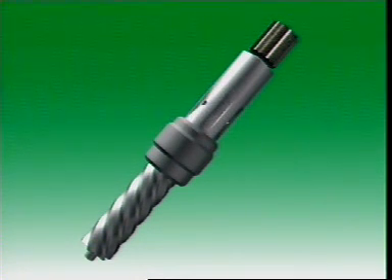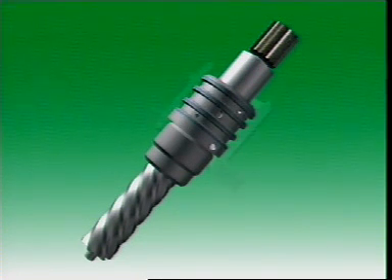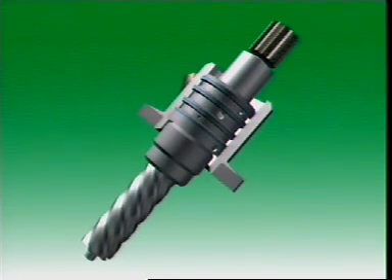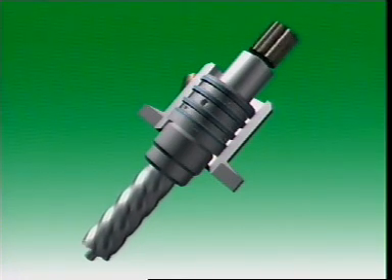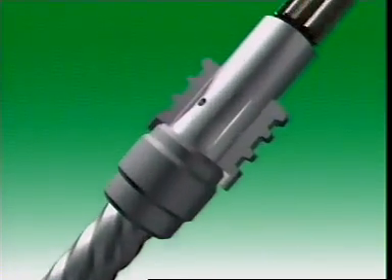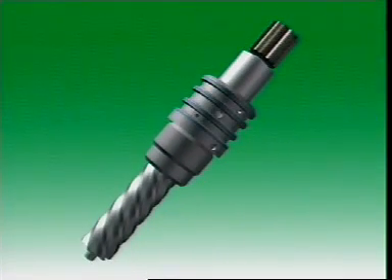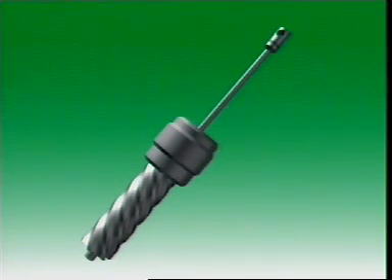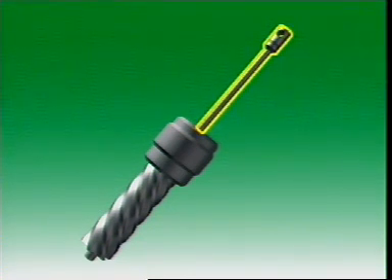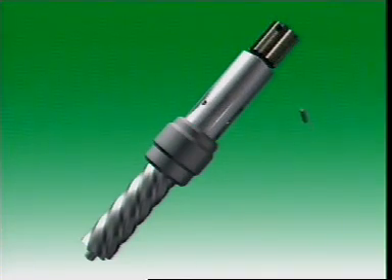It consists of an inner member, which forms part of the input shaft, and a surrounding sleeve member fixed to the pinion gear. Turning the steering wheels makes both members rotate in the steering gear housing, but it is the slight relative rotary displacement of the inner member and the sleeve member which controls and directs the power steering fluid flow. This slight rotary displacement is allowed by a torsion bar, which is connected to the pinion gear at its bottom end and the input shaft at its top end.